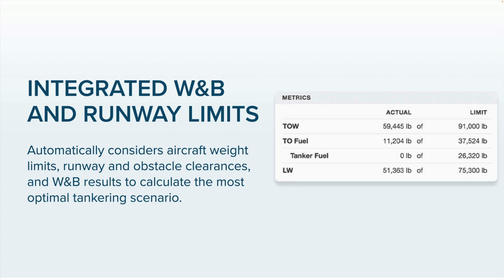And lastly, as Fuel Advisor is performing this tankering calculation, it is also taking into account these other aspects of the flight plan, such as weight and balance limits and runway analysis limits. It's actively running those calculations, and if the weight and balance or the runway analysis calculation imposes a lower maximum weight limit on the flight, Fuel Advisor will know about that, and it will take that into account and make sure that you're not planning to carry more fuel than you would actually be able to take off with based on the weight and balance and runway analysis calculations.